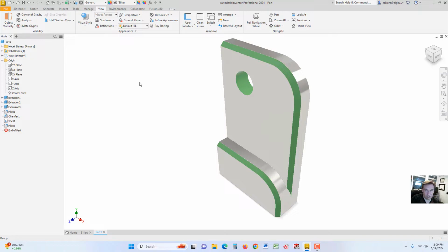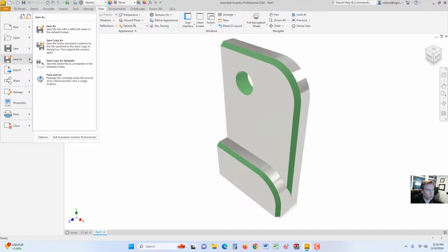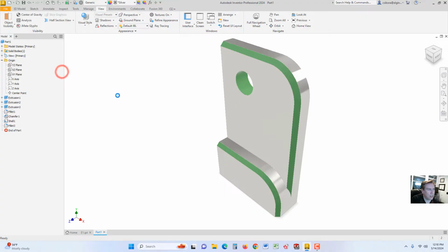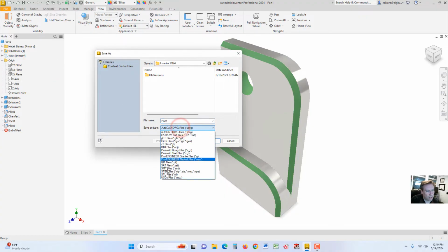You could take this and send it out as an STL, and there's different formats, and all of you who have 3D printers know. You could comment below some of the different settings, there's the manufacturing, there's all sorts of settings. If you export, you'll see there's CAD format, and in here under CAD format, you'll find all these different ways you could export this. There's IGES, or there's SAT, and there's STL and USDZ. There's a bunch of them. STL is one of the basics, runs basically on any 3D slicer program, but there's others that are out there too, that are in here too.